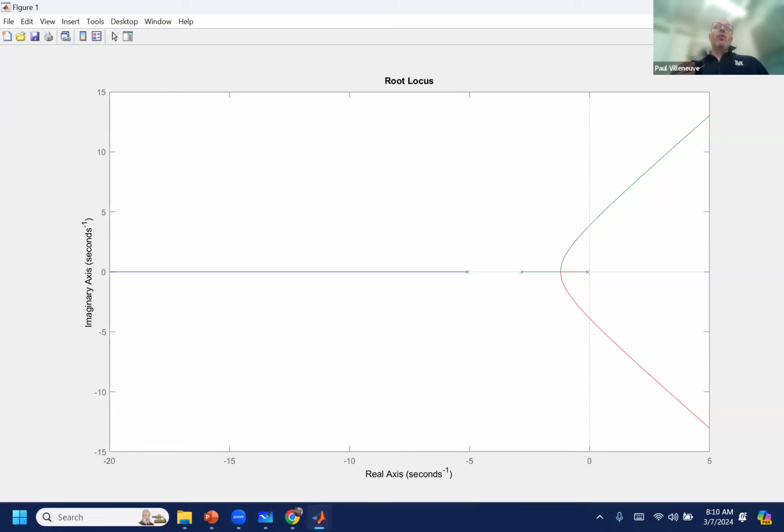So in a root locus, K is variable, and if you're allowed to increase the value of K, that's going to change the roots. As you increase K larger and larger, approaching infinity, your roots start at the poles, whatever those are in your base equation, and then they end at your zeros.